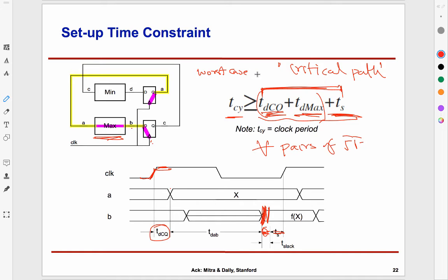So for example, one very common thing which is done in our processors is that every flip-flop in the system is chained together. The idea is that when you're trying to debug, you give one clock tick, and then you extract the state of all the flip-flops and examine it. Then you do one more clock tick and do the same process until you identify what might be happening. So there are special test ports on the chips which help you do that. If you've ever played with hardware, you might have heard this term called JTAG, which is a special port for this purpose.